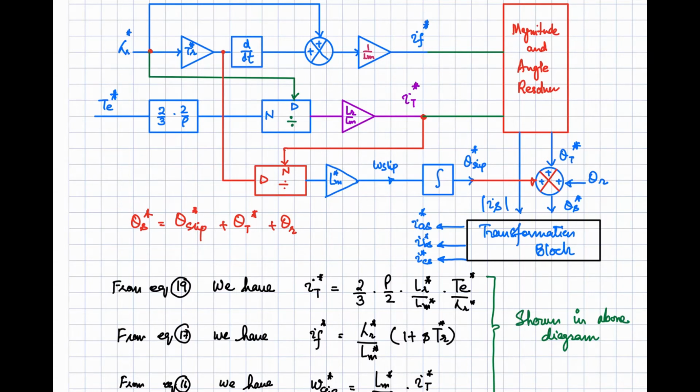In the last video, we have seen the indirect vector control of the induction motor. In the indirect vector control of the induction motor, we determine the cos of theta e and the sine of theta e, which are the unit vectors and are used to convert your current from one frame of reference to the other frame of reference. These unit vectors are computed using theta r, and that is estimated with the help of the information of the speed. So speed is measured and is used for the field oriented control.